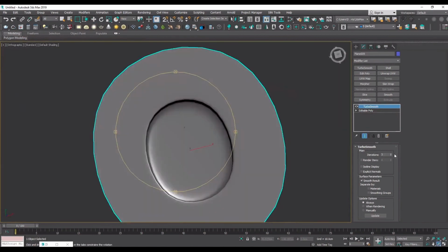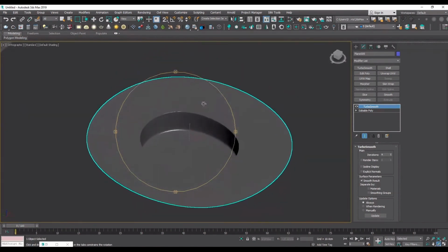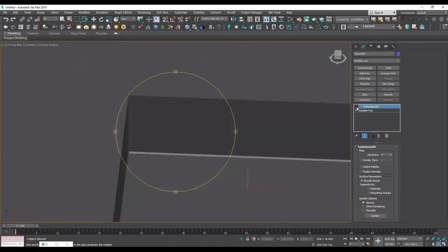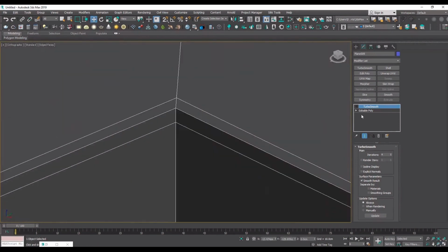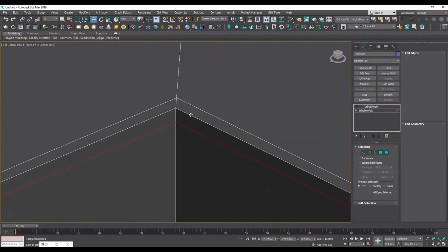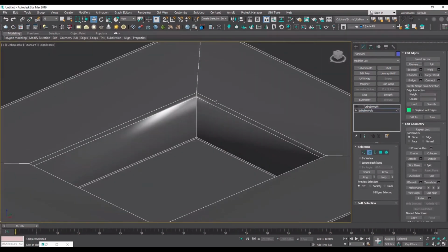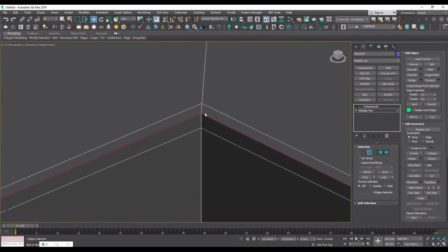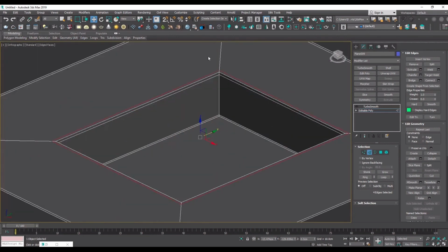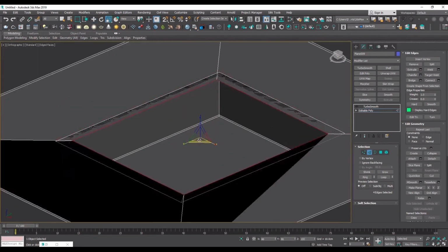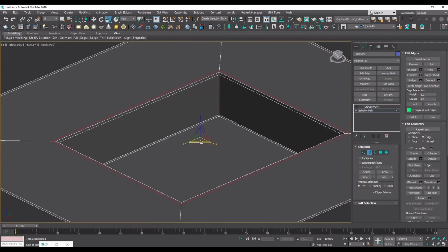and I think so. See, the oval shape we get now is being limited by the edge loops we inserted. Just like before, I want to turn this fillet corner here into a sharper, more defining edge. With a double click, I select the loop and Control-Remove to see if it's enough. But quickly let me undo and first create more distance between my edges using edge sliding. I set my constraint to edges and move my edges a little bit further.